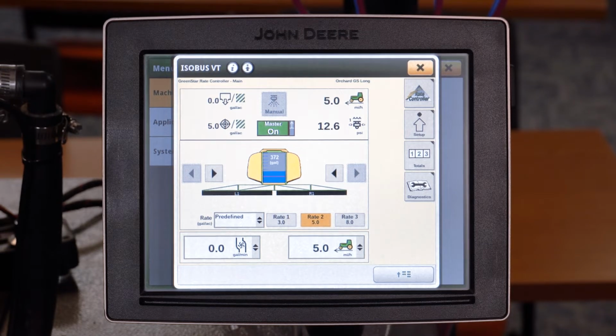First questions to ask would be, when did this start? Has it been working previously? Are you testing or are you in the field? If you're in the field, what message or messages did the controller give you? If there are no error messages, the controller is not expecting the pump to run. If you think the pump should be running, why does the controller think it should not be running?